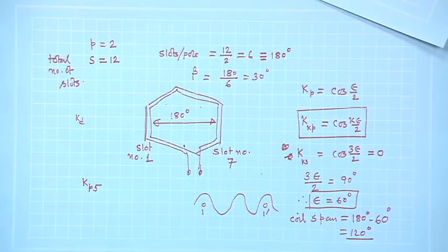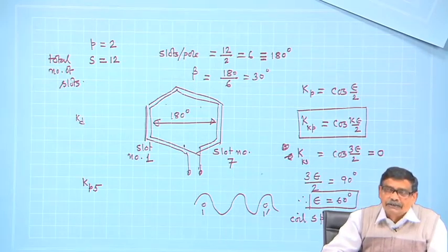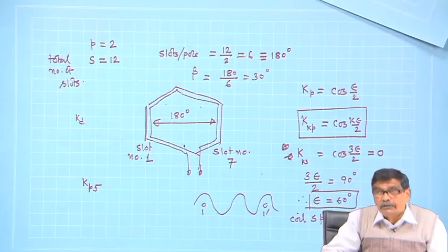We will see in a 3-phase machine that in the line to line voltage, even if third harmonic voltages are present in the coils, they do not appear. So maybe at that time you will be interested in nullifying the fifth harmonic voltage to 0.